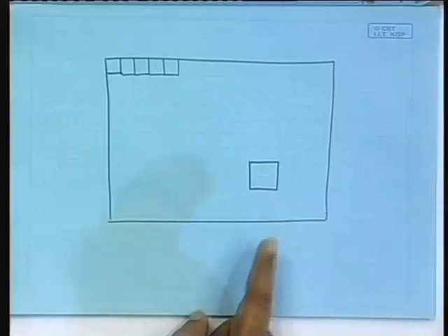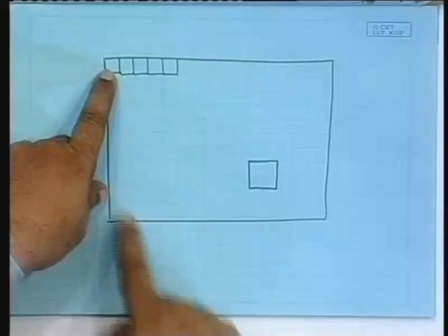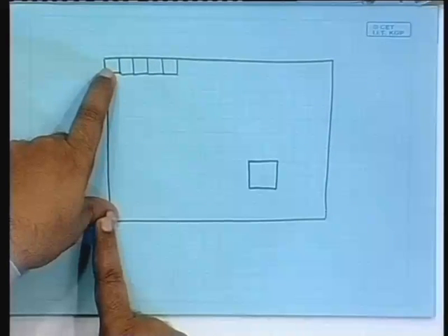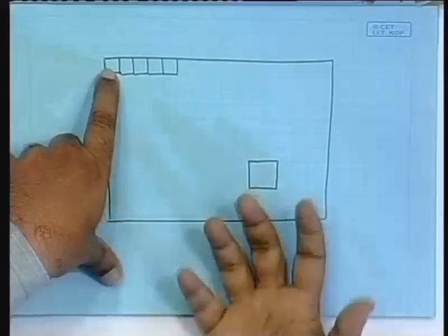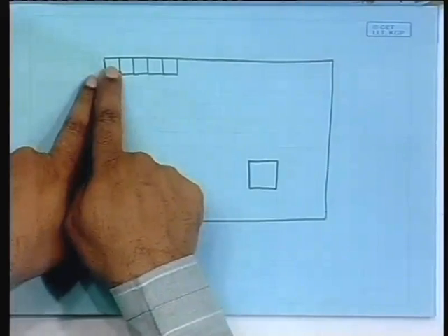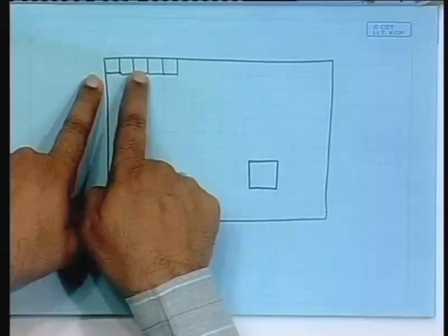You have to search for 16 by 16 all through the image. Yes, that will take a lot of time, because for each one you are searching the whole image. That is why this is very computation intensive. The compression stage is very computation intensive. What people have done is that since searching for this one and searching for this one and searching for this one can proceed in parallel, normally this is done using parallel processing. Initially they used to do it by parallel processing. Now parallelized chips are available, specially designed chips to do this work.